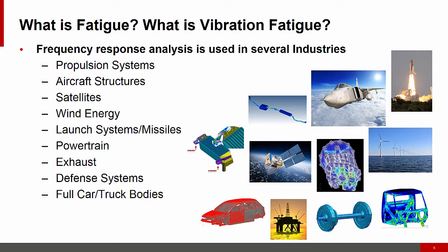Now, why do we have to care about the dynamic features or vibration fatigue? What is vibration fatigue? All fatigue is dynamically induced. That is, there must be some level of dynamic loading in order for fatigue damage to occur. Now, for a long time, engineers have known that frequency domain methods for structural analysis offer very qualitative information about the structural response. That's why it's important to understand the behavior of the structure in the frequency domain.